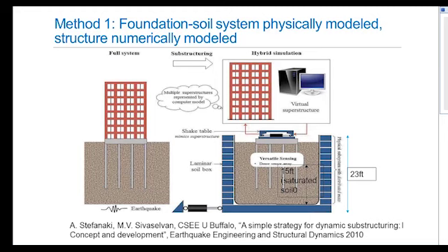So this is the test that was done at University of Buffalo, 23 feet high laminar box. The soil was saturated, so they were trying to evaluate the liquefaction potential at these various instantiations of the test.